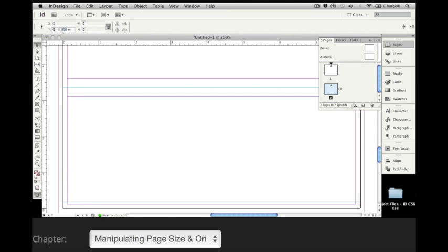I'm going to take that and highlight this, and I'm going to put exactly .1875. It's going to place that guide precisely at 3/16 of an inch. Now I need to do the same thing here at the top of the panel.